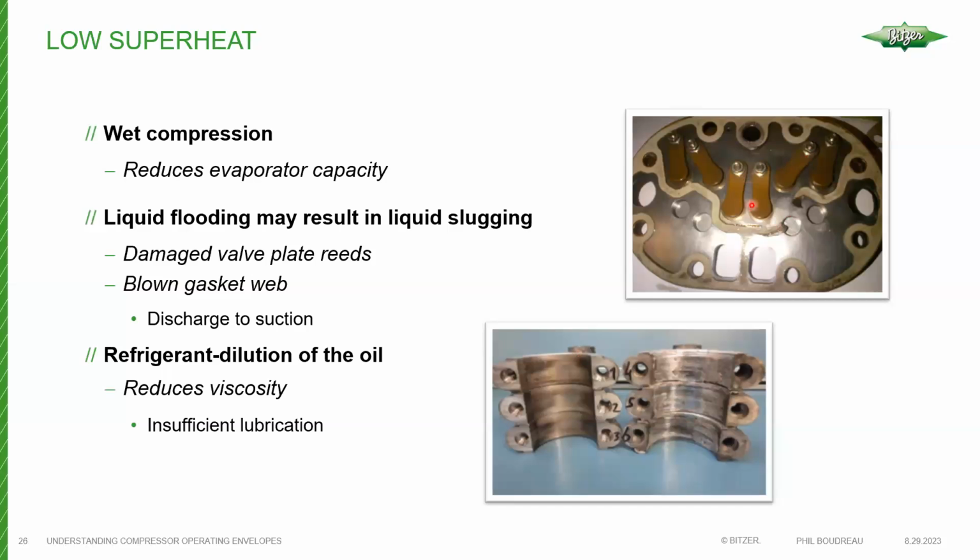This sort of thing up here, broken reed valves and what have you, is generally the result of operating the compressor outside the envelope, high compression ratios, and more commonly, I would say, liquid slugging.